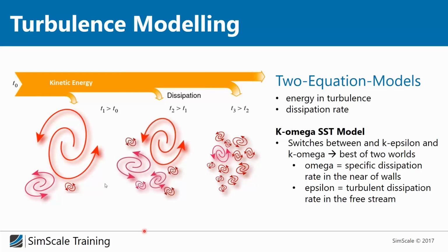Vinaka wants to know if SimScale also supports large eddy simulation. Yes, we support LES simulation. However, for those of you who don't know what it means, LES means large eddy simulation, and it's something between DNS and a turbulence model. So you do a direct numerical simulation for large scales, and for smaller scales you use a turbulence model. And we even have some example projects with LES in our library. However, for automotive applications for most students, I would not suggest using LES. It won't help you.